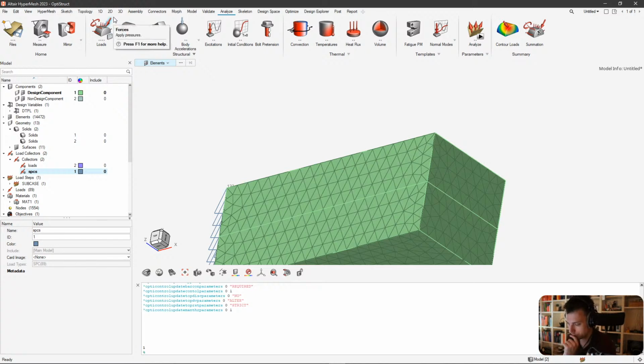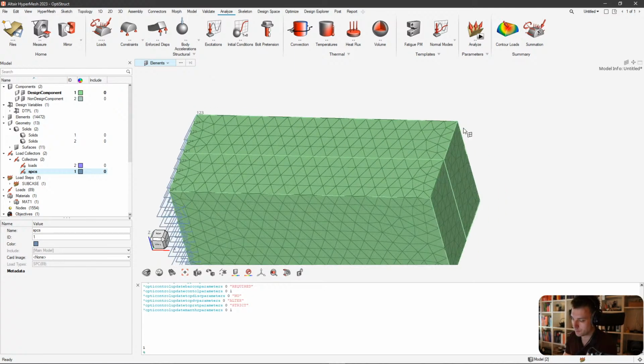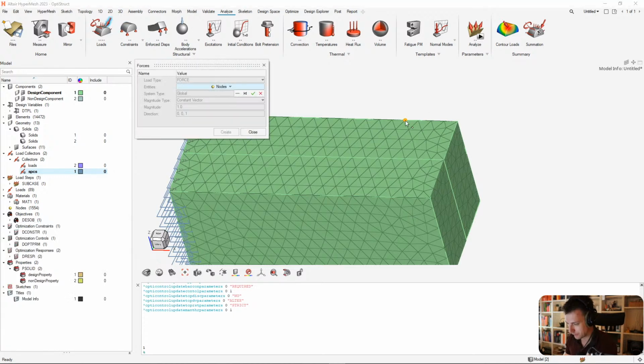Eventually that's what's happening. Because I'm staying away from using RBEs here, because we just had the edge, and if you're doing an RBE there, there's no lever around a particular axis, and that's a problem. So I'm staying away from the RBE stuff.